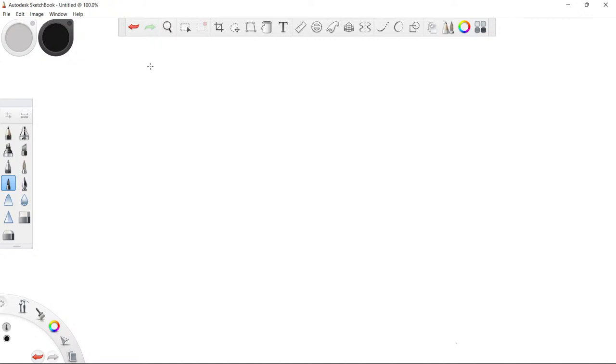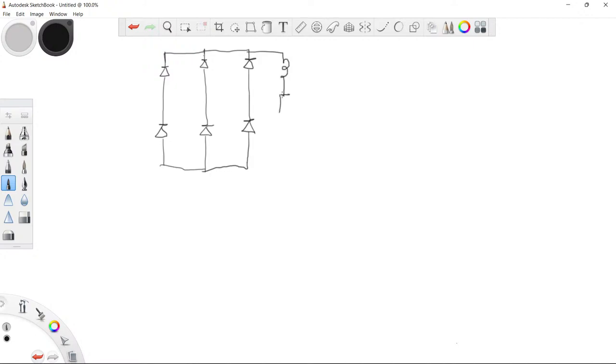Let's see now. We saw the single phase diode bridge rectifier as this, right? We had diode 1, this, so this is what we saw. Then we had a source connected here. Now with the three phase diode bridge rectifier, you add another leg, another diode leg like this. So you have it like this. Then go through your smoothing inductor through to your load like this.